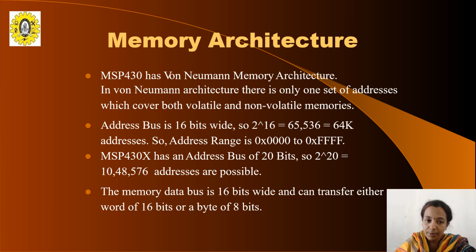The MSP430 architecture follows the von Neumann architecture. In von Neumann architecture, there is only one set of address which covers both volatile memory as well as non-volatile memory, which means the erasable programmable read-only memory and also the random access memory and also the read-only memory.